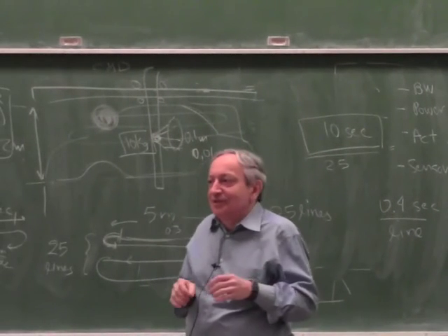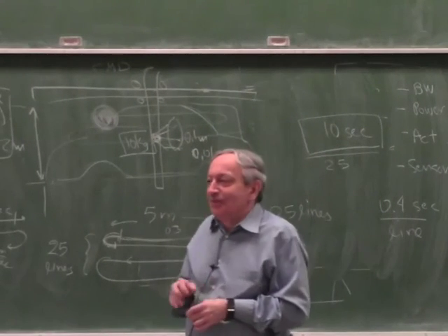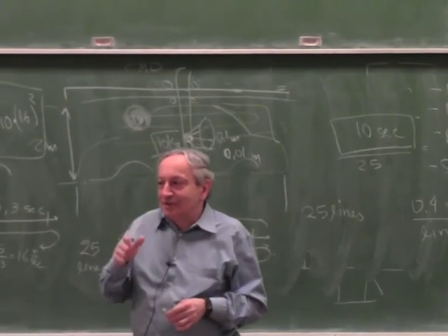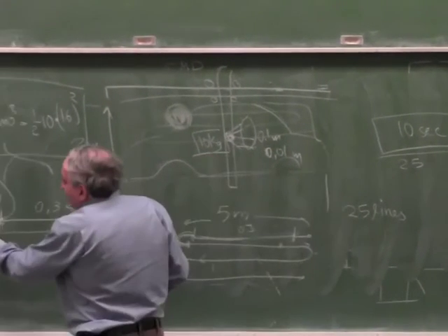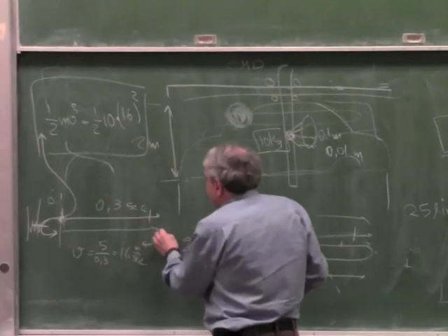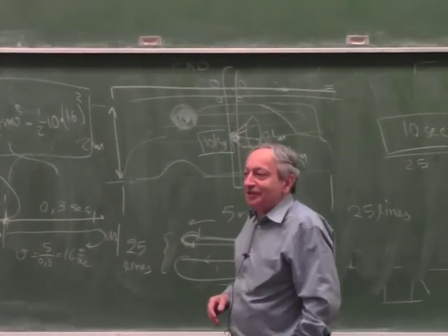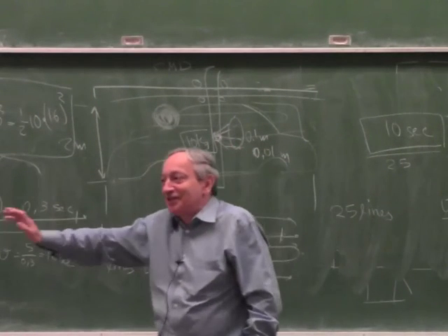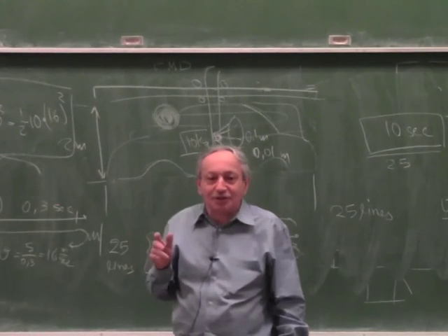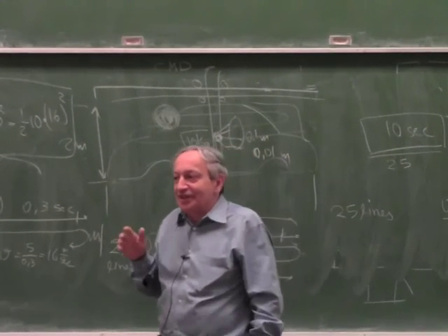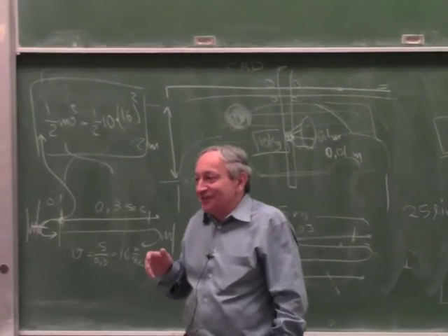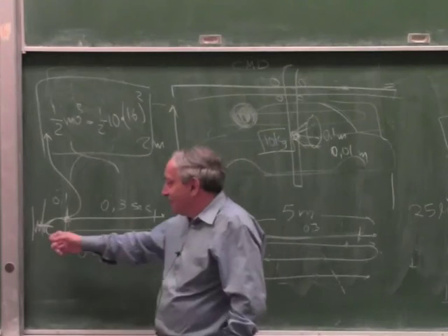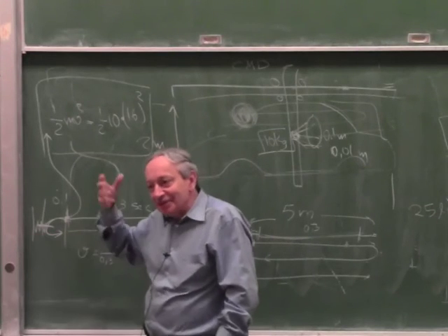The reason why it's crude, because if you are a smart student, you immediately say, let's put some spring bumpers here. If I put a spring bumper here, I don't have to do anything. It just hits a spring, compresses it, and re-accelerates. And I just have to add the friction. So the difference in the exam between A and A plus is, if you just calculate it right, you get an A, but if you see that you can do something simple like a spring bumper, you get a few extra points.